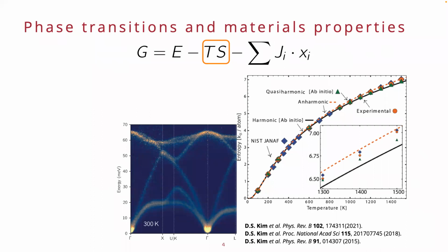That's a very good point. So in this case, I'm just showing the entropy curve for a single phase with temperature. So it's not actually going through any transition. I'm only seeing the deviation between different theoretical models. So what you would need to do in this case would be to get this curve for the diamond cubic phase and then also compare that to, let's say, your HCP or a different phase to make that comparison.